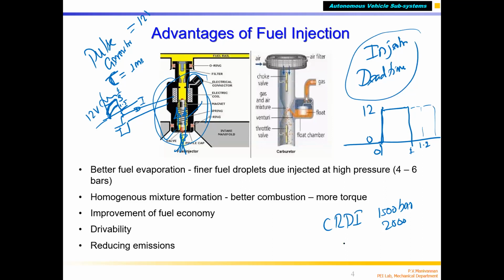You won't even know it if you put your finger or body near the jet, correct? The diesel fuel will go inside your body, and you won't even notice. It will be a painless injection, but you know that injecting diesel is highly dangerous. If it enters the bloodstream, the brain, everything will be swollen. So never go near the fuel injector nozzle during CRDI engine testing, correct? That is very important.